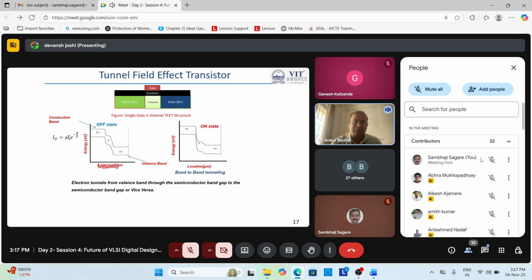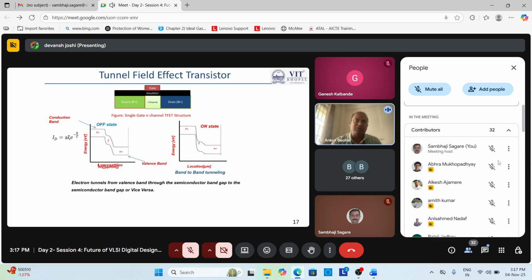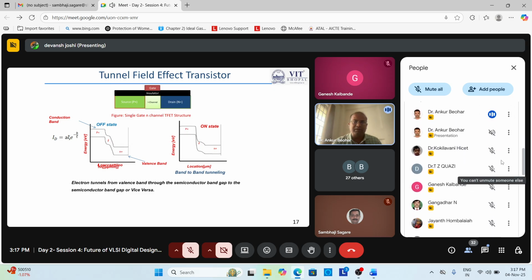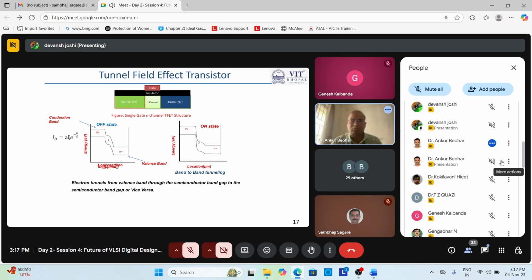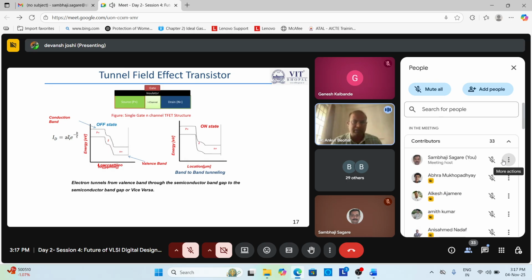And here the subthreshold swing will also be possible to go below 60 millivolt. I mean 0.35 or 0.05 volt is also sufficient. In order 0.05 we have incremented, your drain current suddenly increases like that. So the subthreshold slope is low in this kind of device. We have some other devices also like graphene, MoS2, but the only problem is their controllability.